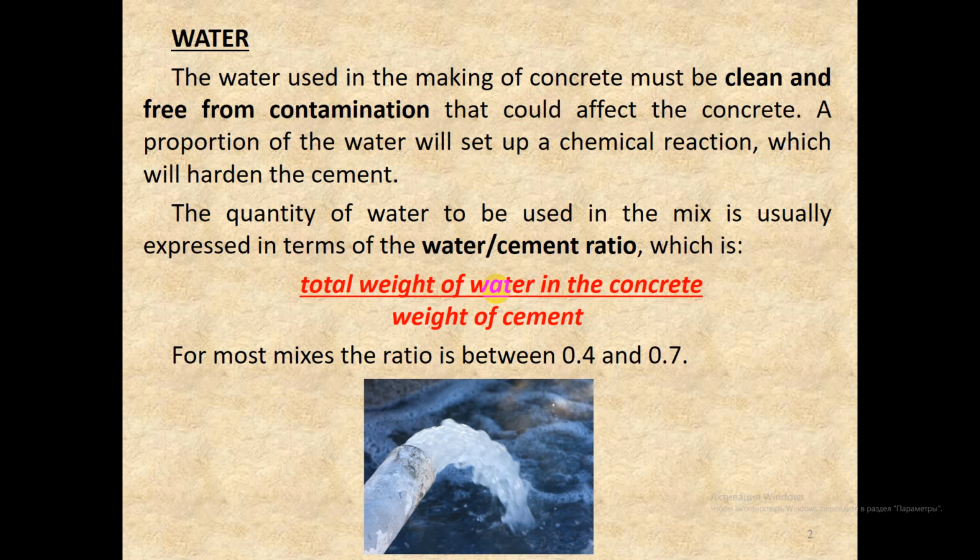Water in concrete has two important functions. First, it mixes with cement powder and results in the hydration reaction commencing, which ultimately results in the concrete hardening. But the concrete also needs to be placed, and the term used to describe this is concrete workability. To be workable, concrete needs more water in the mix than just for hydration.